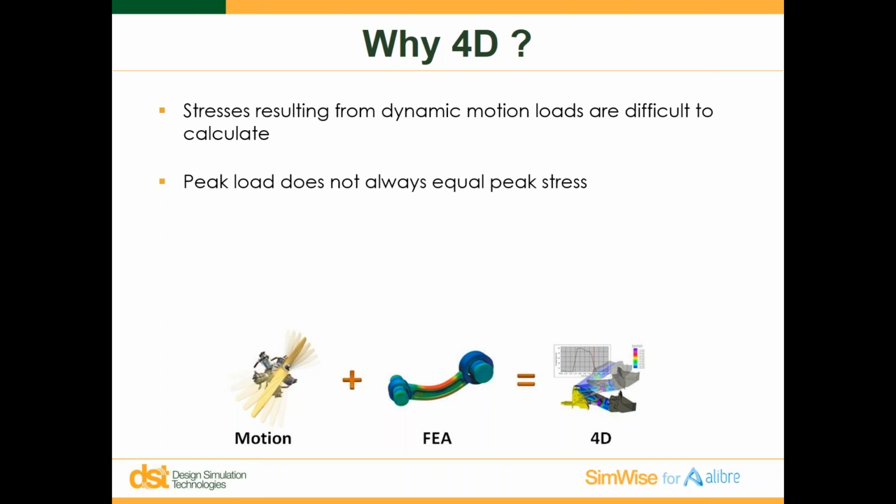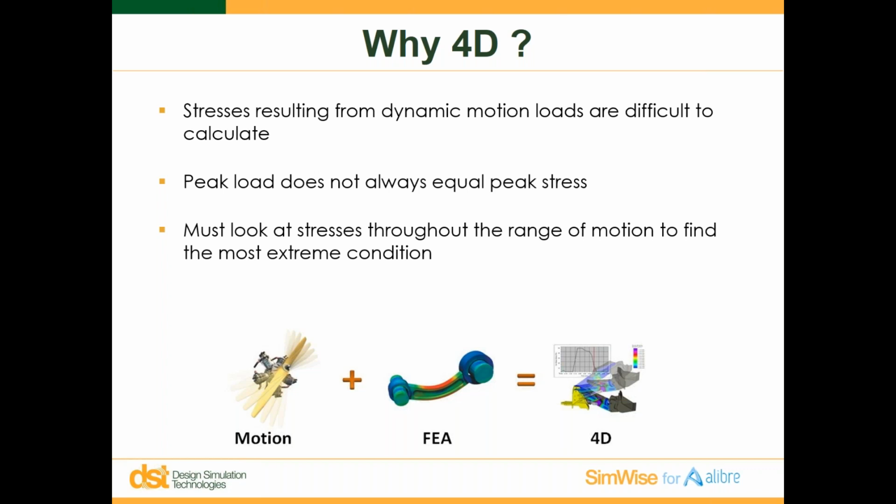So you could do a motion simulation, look at a graph of some forces and see where that force is at a peak, and then do a finite element analysis using those loads. But what you may find is that in that particular configuration, although the loads are high, the part is designed to handle those loads in that configuration, and the stresses are low. It may turn out that the high stress condition occurs at a different position with lower loads.